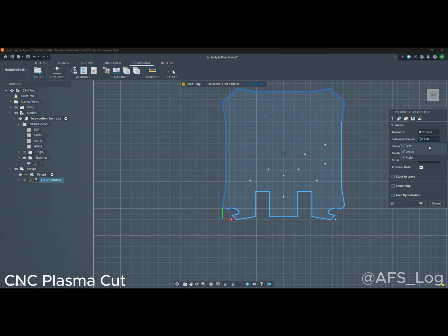It's going to cut here first, then cut here. If you remember the initial one, I selected this, then selected this, then selected this. Then that is how the machine is going to go all around, cutting them in the exact order I made the selection. But if I remove this preserve order, the machine is going to try to optimize. Fusion 360 is going to try to optimize my selection, the G code, and try to make sure the selection is as close to each other as possible. But I always like using preserve order.